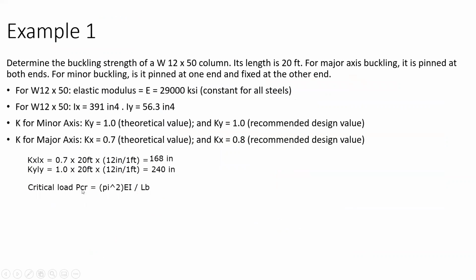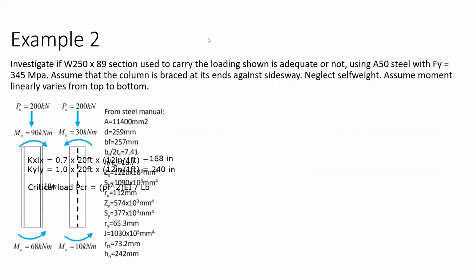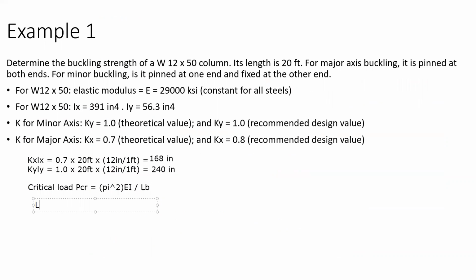That is P is equal to pi squared EI over Lb squared, wherein Lb is now equal to your KL.